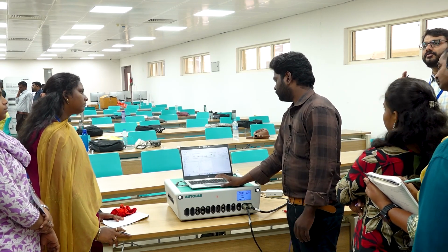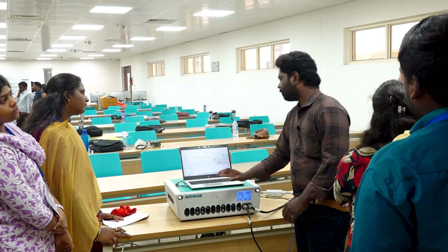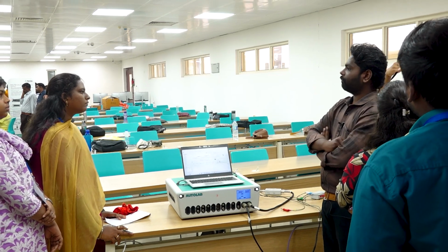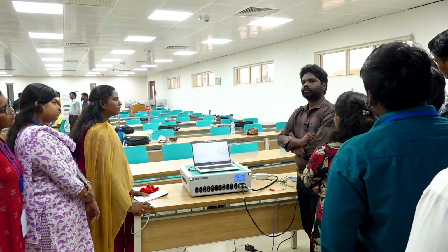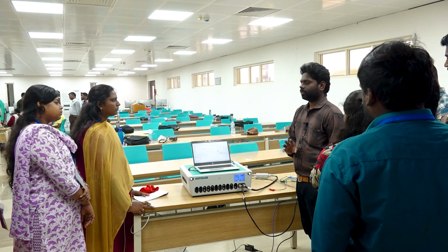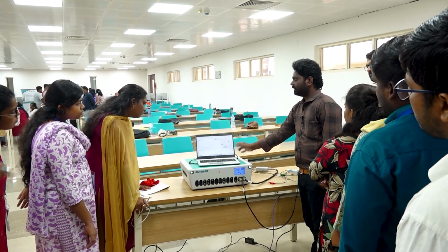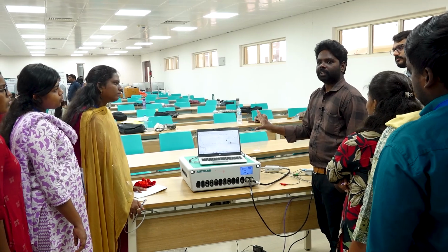Another practical application: if you are fabricating a solar cell, our input source is actually sunlight. Sunlight is not a single frequency, it's a group of frequencies, so we have to accept all these multiple inputs. That's another reason for testing your device in a large range of frequencies. So simply, we are applying 100 kilohertz to 0.1 hertz.